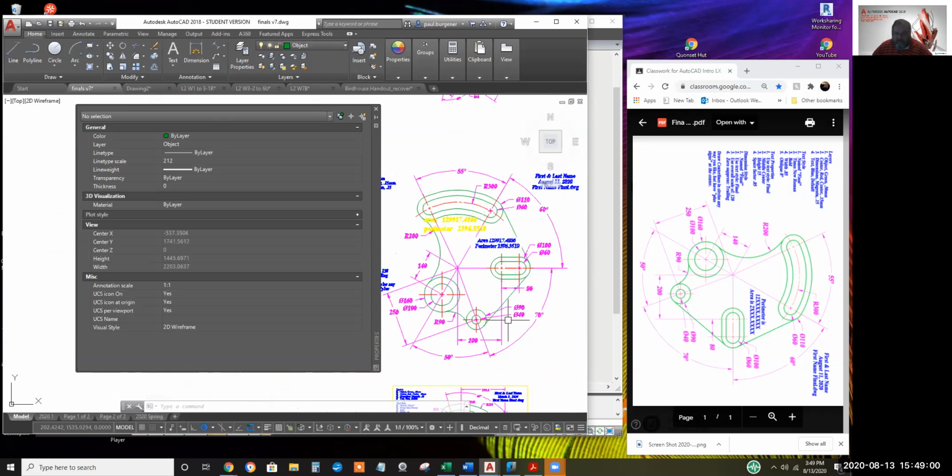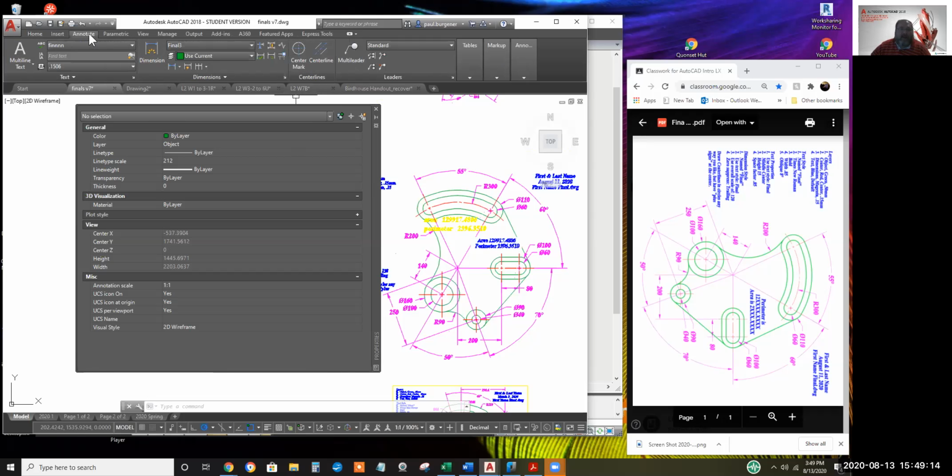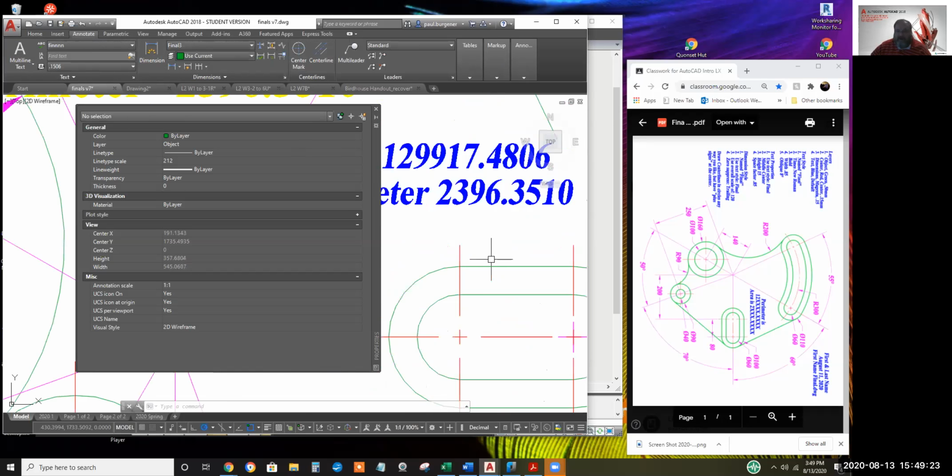Again, since I really don't know how industry makes center marks in circles, there is the center mark icon right here on the annotate tab. But again, you have to make adjustments to how big the whiskers are outside of the circle. And you have to make adjustments for each and every circle if you want the extension to be proportional to the diameter as I like.